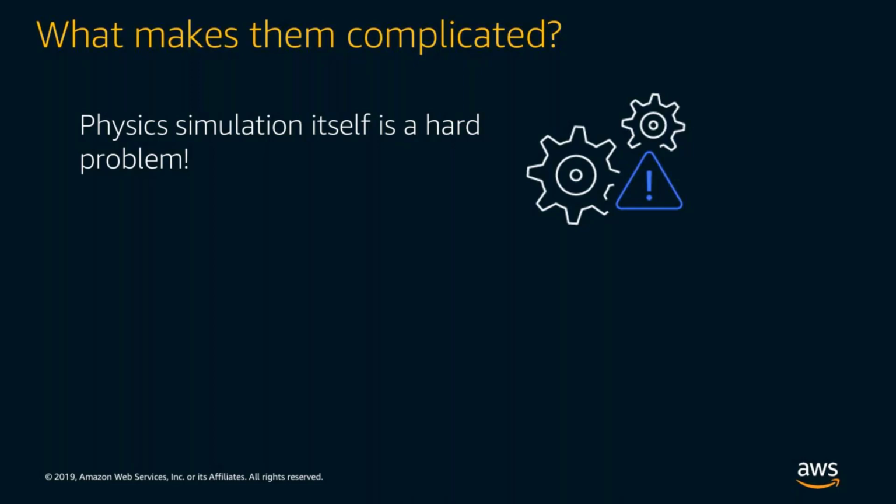For example, in a typical rigid body collision process, there are usually two phases, a broad phase and a narrow phase. Completely different techniques are required for each phase, since broad phase algorithm is usually dealing with a massive number of objects, while it may not need precise results between each individual pair. While the narrow phase algorithm is usually dealing with a specific pair of objects, but somehow needs more collision info between them. In addition, sometimes one also has to make trade-offs between a more precise result and the overall performance, especially when it comes to real-time simulation, which is essentially what Sumerian is targeting.